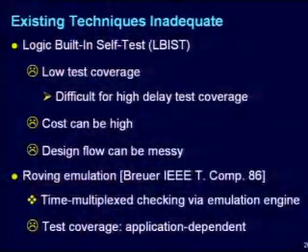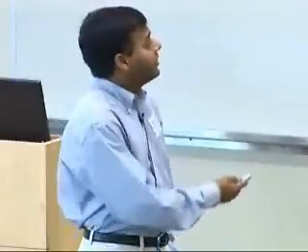Now, let's look at some of the existing techniques for online self-test, and they are inadequate. For example, you could think of logic built-in self-test, or LBIST, which I'm sure many of you are familiar with, or at least have heard about. Logic built-in self-test has very low test coverage with respect to delay faults. You cannot get very high delay test coverage out of random patterns, which is what logic built-in self-test uses. Cost can be very high, and the design flow can be really messy. So that's why people haven't even used logic built-in self-test in a big way, even for regular manufacturing tests.